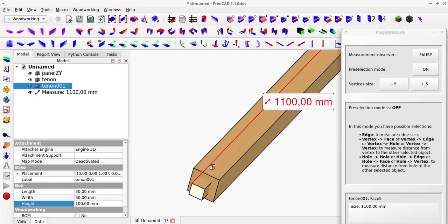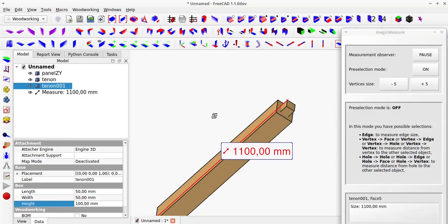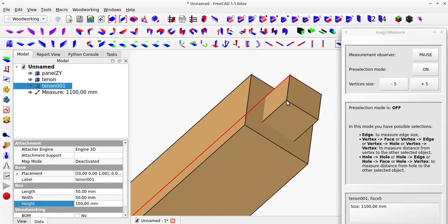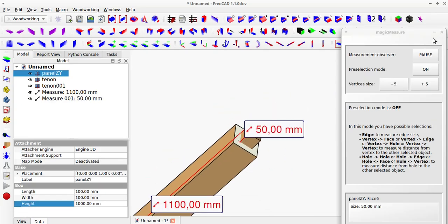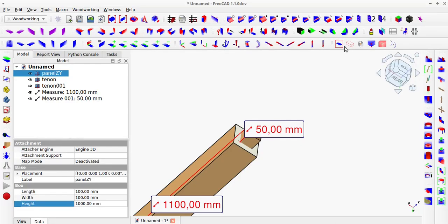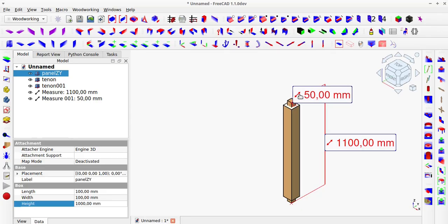The default size of the tenon is determined by the face size with an offset around of 1/4 of the object's thickness. Its total length is the same as the object's thickness, but it is halfway hidden within the object. Therefore, in this case, the total length of the element is increased by its thickness.